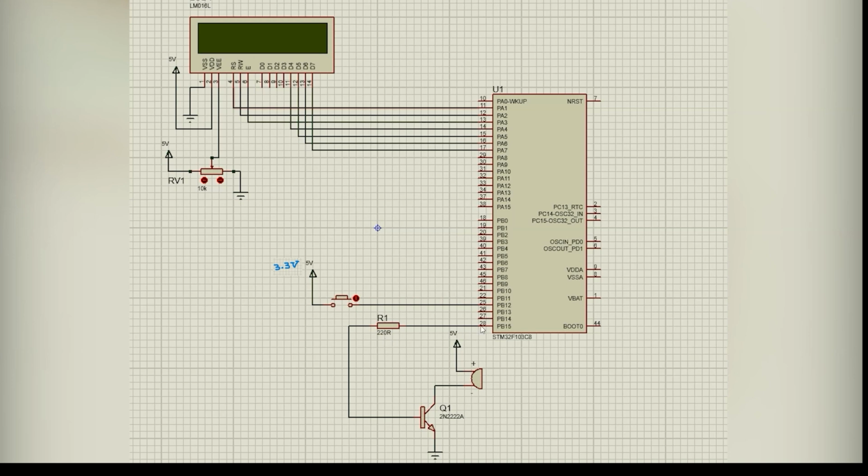And so when the command comes from the microcontroller and it is set to 1, logic 1 comes here, and then this transistor, which by default is open circuit, is short circuited, and the buzzer circuit is closed and it creates a sound for us. And the buzzer also works with 5 volts.